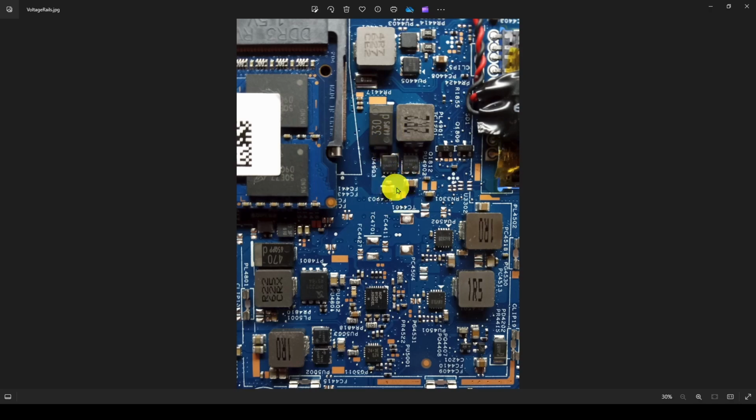how the power management is configured to turn on and turn off the DC coming in from the wall adapter. We also talked about what you see here, which are the DC to DC converters that convert the 19 volts coming from the wall adapter into the lower voltages required by the components on the motherboard. We also talked about simulating those in LTspice, which is a free electronic simulator program that is really important to learn if you want to understand electronics. So we showed you how to simulate these circuits.